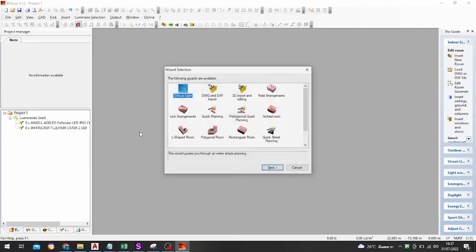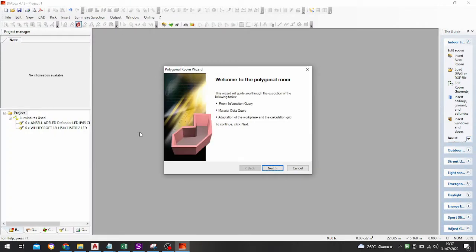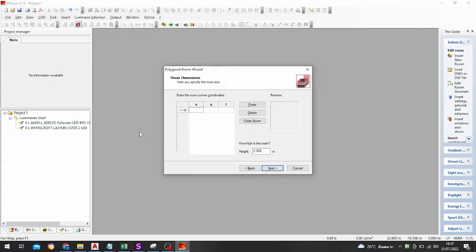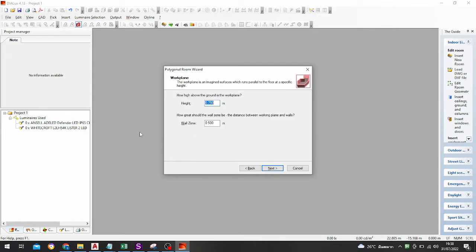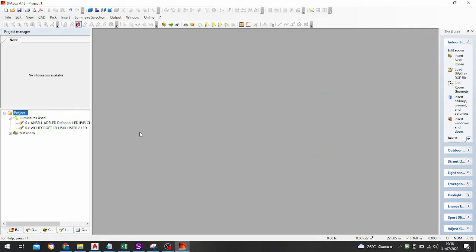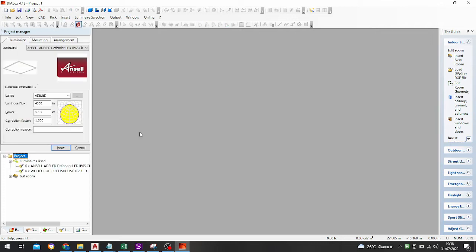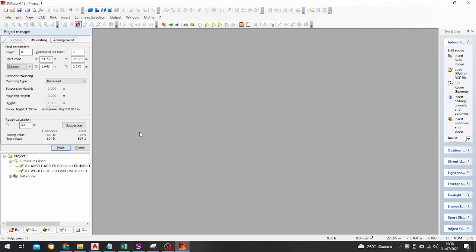I will make it start, and now I can just go for a coffee or whatever, because the Dialux will work alone. As you can see, the cursor doesn't move. And in a few words, the Dialux is now building all the 8 different scenarios we just saw on the Excel. So it will build the geometry, all the field about the fittings, and will export finally the summary sheet at the specified path.